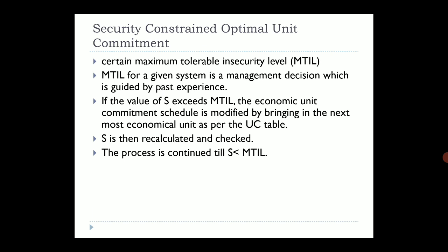The MTIL for a given system is a management decision which is guided by past experience. If the value of S exceeds MTIL, the economic unit commitment schedule is modified by bringing in the next most economical unit as per the UC table.